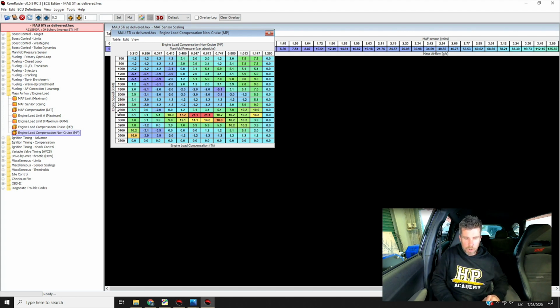We've got our engine RPM on our vertical axis, and our manifold absolute pressure on our horizontal axis. This is kind of just a way of adding or removing fuel based on what is required. And straight away, if you look at some of the numbers in this table, particularly around 2800 RPM and in vacuum, so cruise areas, you can see we've got numbers peaking at 21%. So that's how much additional fuel is being programmed to come in there. So interesting that an OE manufacturer decided to put a software band-aid on a mechanical problem, yet here we are.